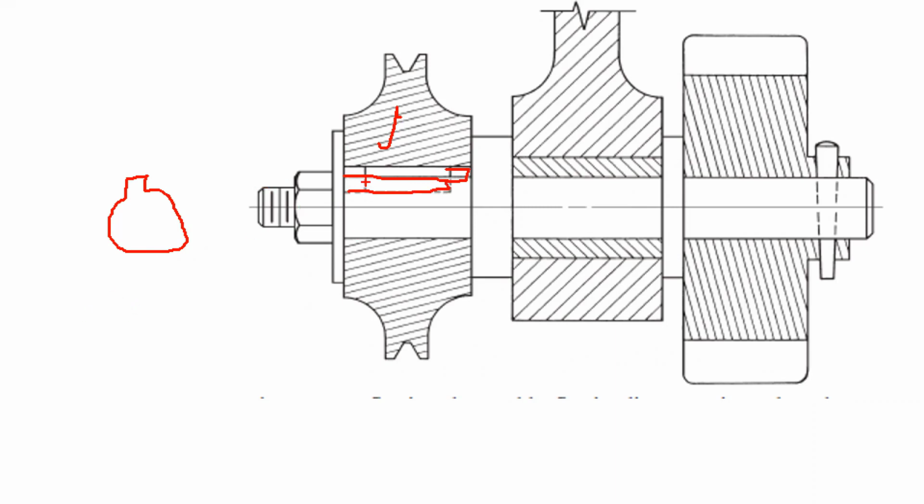So if we crosshatch right there, we cut this and look at it, the shaft down here will look like that. And the key fits down in there. It's not quite that big and slides inside here. It holds all that, transfers that rotational motion.